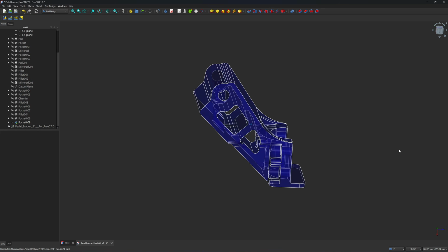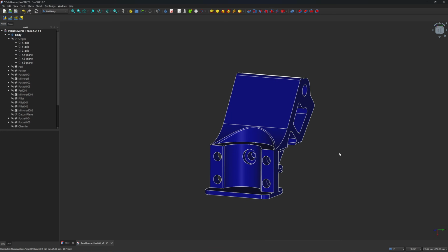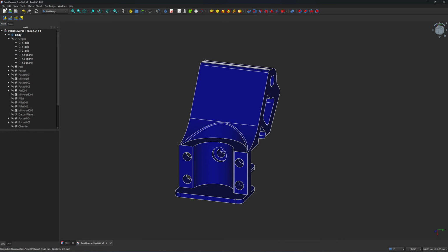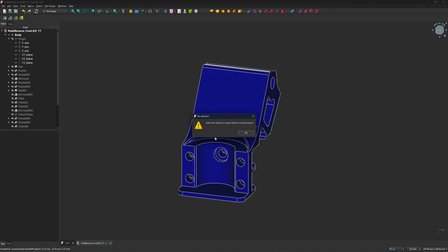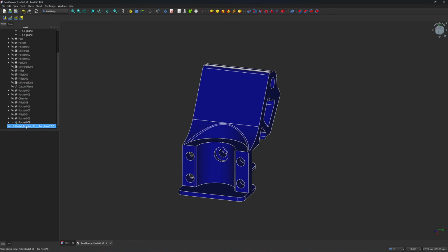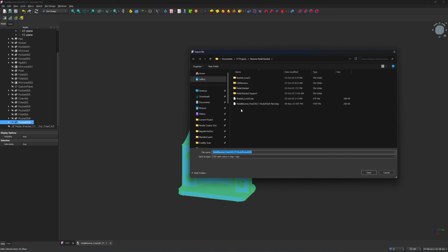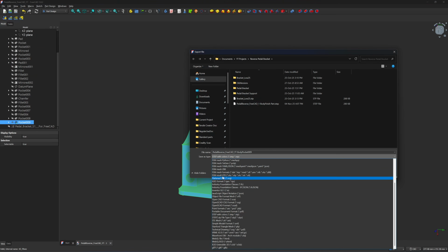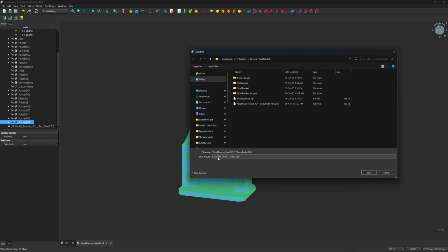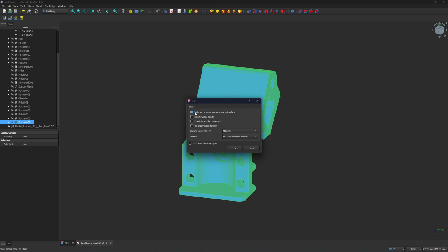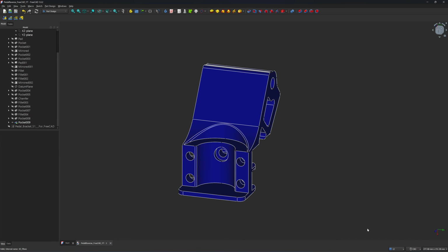This will be the part that you make. Okay, it's time to save and export this file as a STEP file. Export. Okay, you need to click on your last command, pocket, then file, export, and you can export as a STEP file here, STEP, right? Click on save. It's going to ask you something; I didn't click on anything here, use the default value, click on OK, and you get your STEP file.